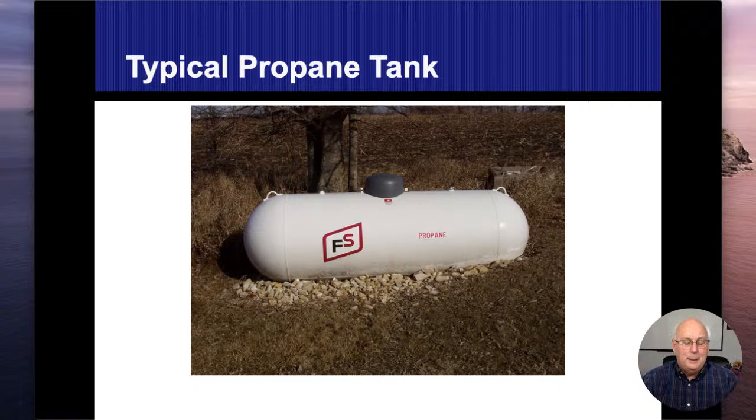But going back to the flammability thing, if you do convert from propane to natural gas, in other words, if I take a propane device and hook it up to natural gas, like let's just say a propane grill, and I decide I want to run a gas line out there so I don't have to buy those tanks again, and I hook it up, I'm going to get a real bad flame coming out of there.